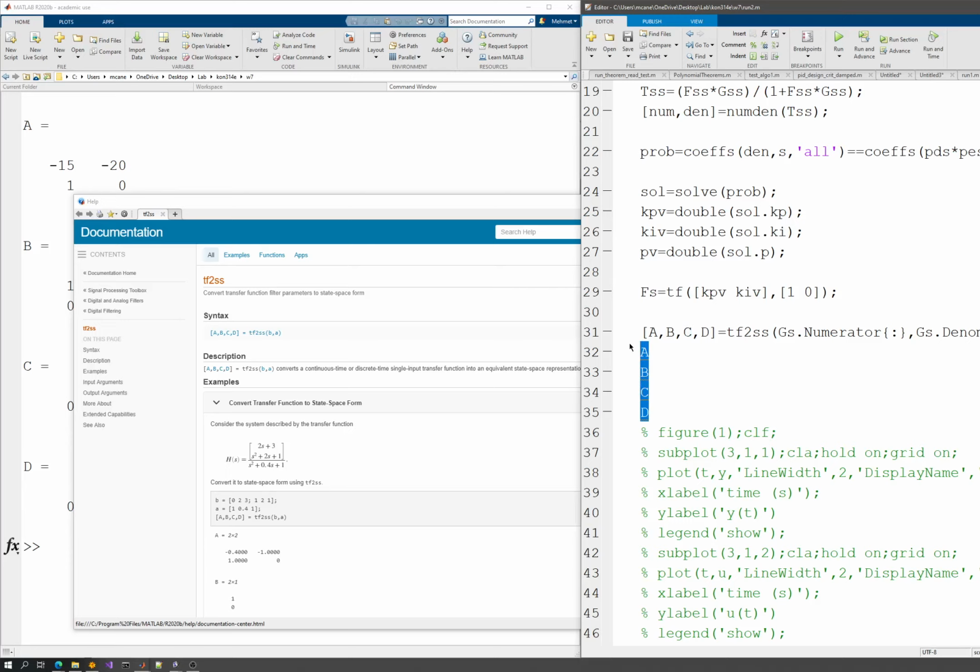If you know a little bit, let me explain to you using Simulink. In Simulink, if you remember, you are dragging and dropping some blocks and connecting them. And if you click one, you can see at the bottom that there is a solver defined. And this solver is basically a differential equation solver. You can use ODE solvers there, 4, 3, 2, 1, maybe also 5. There are some algorithms that are capable of solving differential equations, for example Runge-Kutta or other algorithms. So if you are working in continuous time, you have to use one of those solvers. I might use that as a possibility. You can code ODE, and that's also possible.